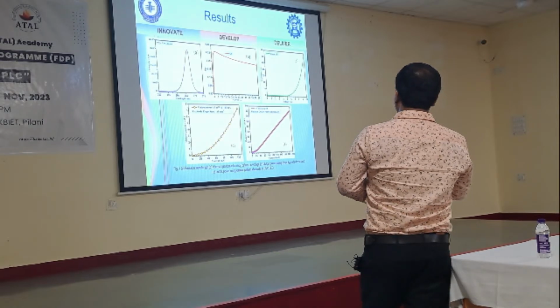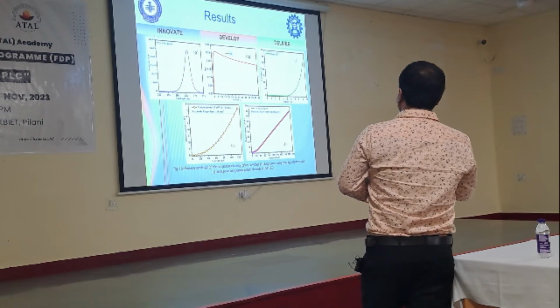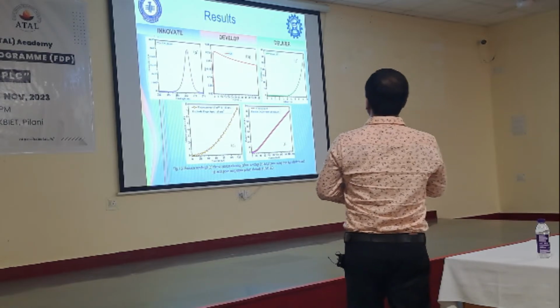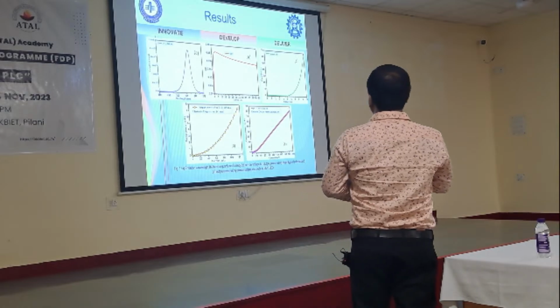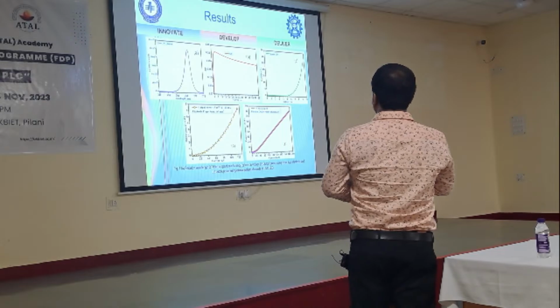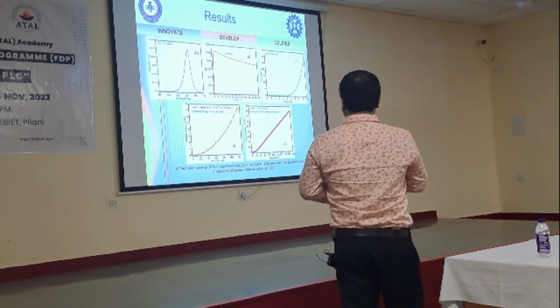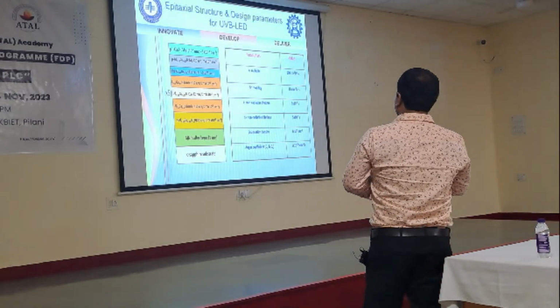What are those electrodes? One electrode is a finger type electrode and another one is a circular type electrode. You see, using the circular type electrode, you are getting a quite higher power efficiency. Output power is 14 milliwatt at 50 milliampere current, and in this case 4.9 milliwatt at 100 milliampere current. And again, another study is there.